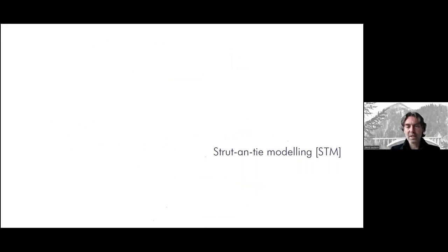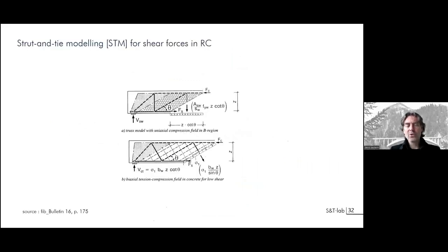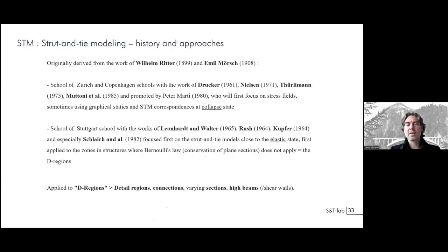So let's move to the next chapter. You know, maybe, this model that is used for calculating shear forces and reinforcement against shear in concrete structures. The story starts actually with Wilhelm Ritter and Emil Mörsch at the very beginning of the 20th century. From this, there will be two parallel developments. The School of Zurich and Copenhagen, with Drucker, Nielsen, Thürlimann, and Whitney, will first focus on stress fields, and from them develop the corresponding strut-and-tie modeling at the collapse state.